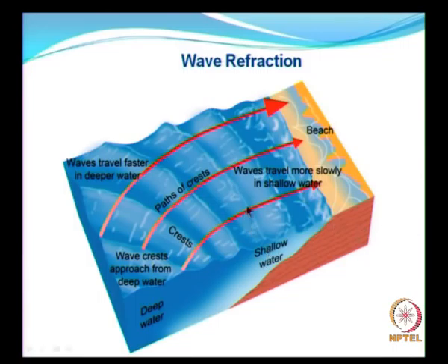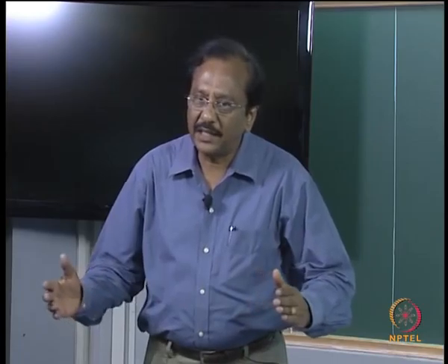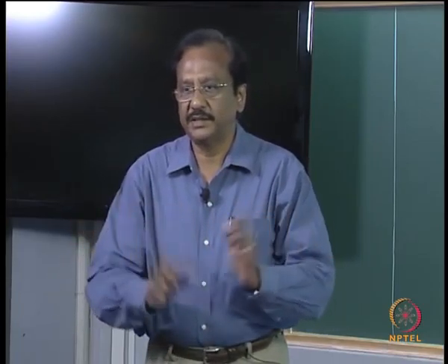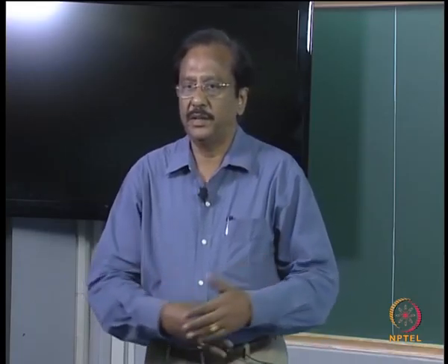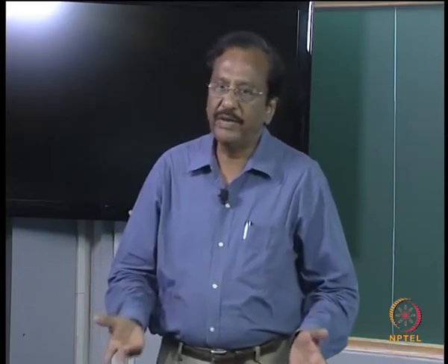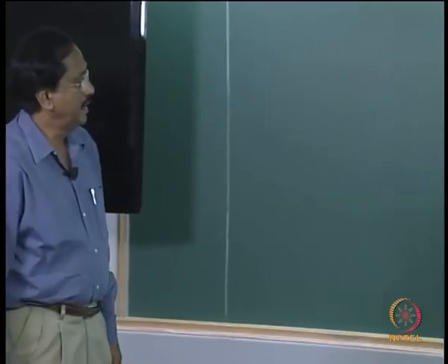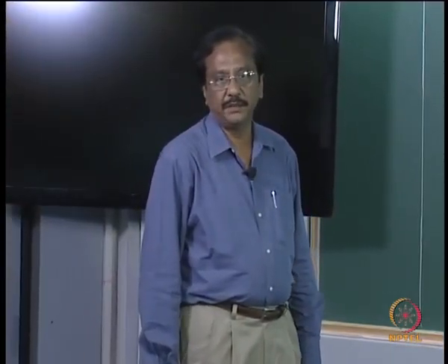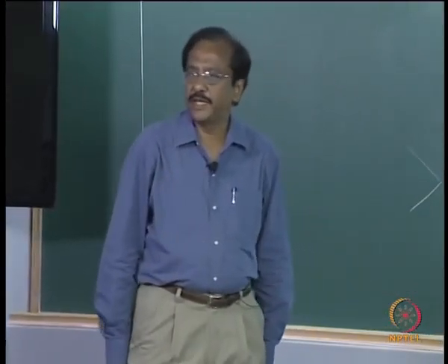What is this wave ray? For example, this distance conveys us something. Depending on the water depth contours, the orthogonals can converge or can diverge. This depends on the seabed topography and your wave characteristics. So, once you try to get a refraction diagram, you can easily understand what a refraction diagram can convey.